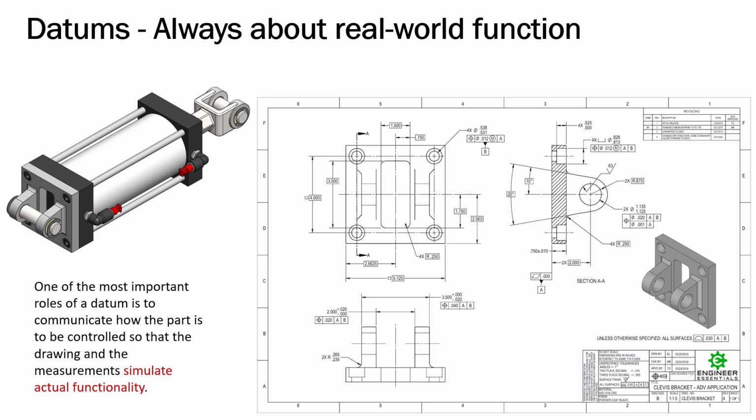They're going to look at this and take an attack on how to get all of the material out of there, rough it all out. It's going to move. The material will definitely move as it gets machined. It's going to stress relieve. So as they go through and machine this, then eventually they will come back and get these datums. So they may rough out all of this material around through here. They may get all of that out and rough it all out, leave a little bit of material for finish.